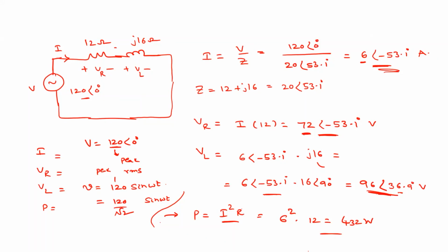Sir, if we consider this RMS, then with root 2 the answers will also be different. This is 120 into root 2 only. Here we represented with peak, and this one we represented with the RMS value. That 120 is RMS. To get the RMS value, we have to take the square root of the integral of i squared dt divided by the integral of dt.